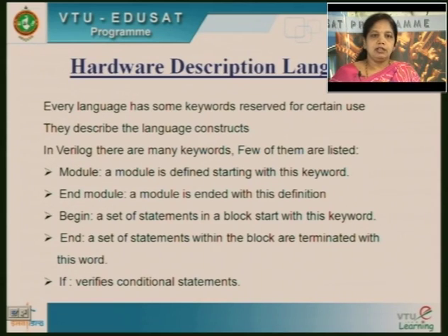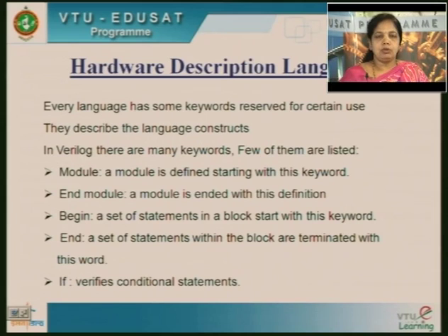Then we have a keyword called begin, which is used before I start a set of statements. Before I start sequential statements, I should declare begin. So, begin is nothing but the start of a block of statements. Once I complete the block of statements, I need to end the block by giving the keyword end. If statements are used to verify certain conditions. Likewise, we have many keywords available in Verilog.